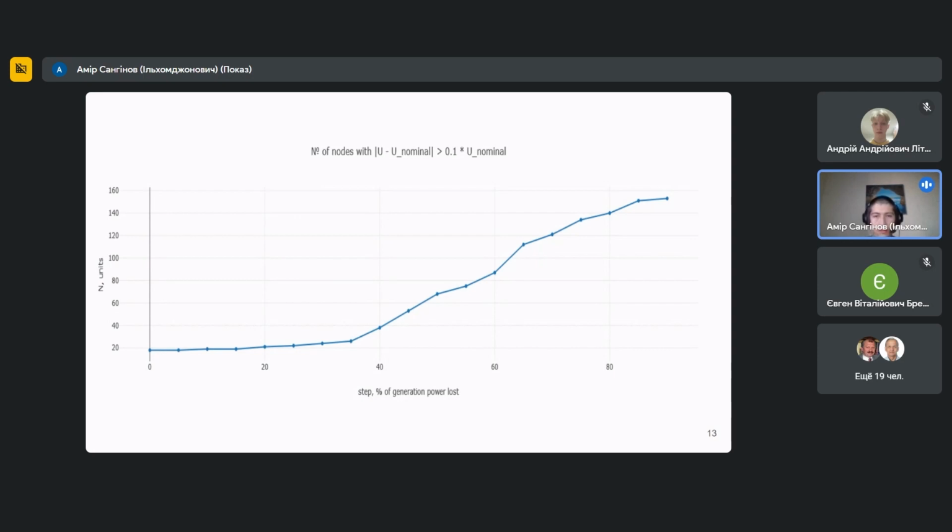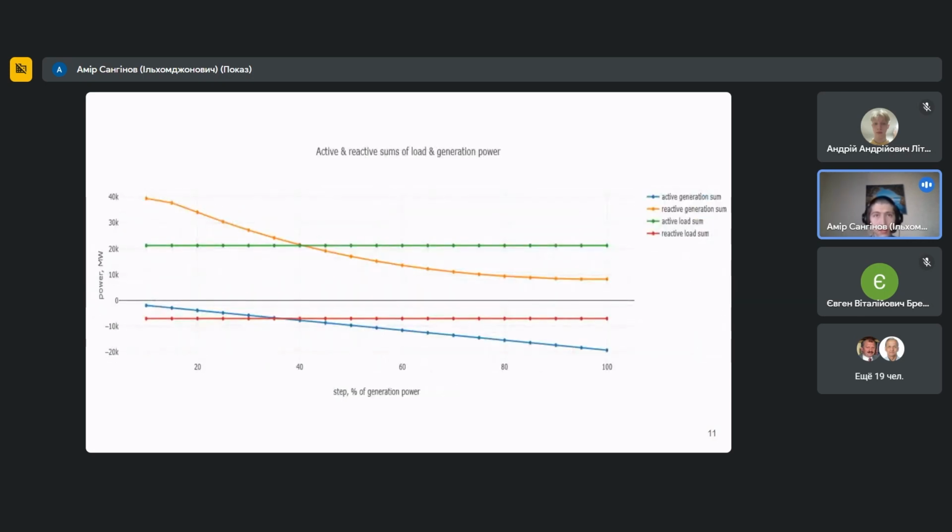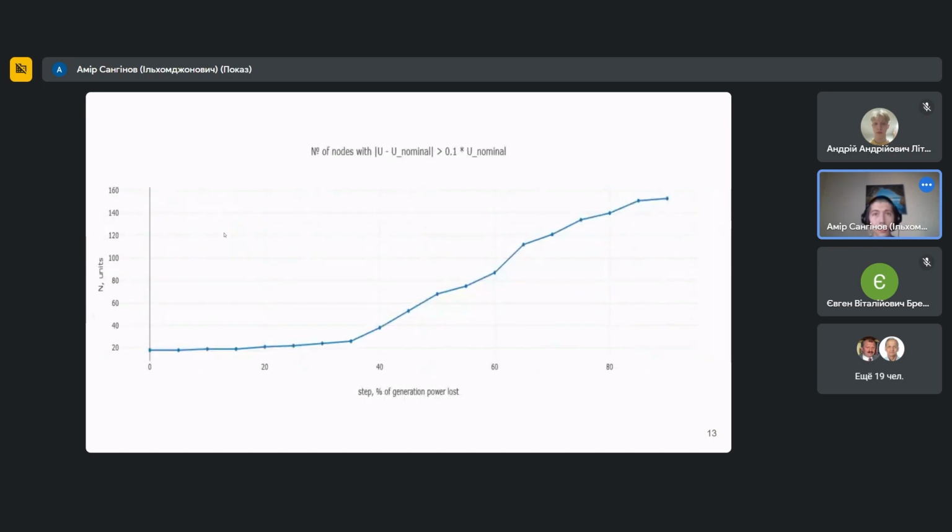We see these results because of the absence of the limits on the reactive power generation earlier, which raises the voltage levels and compensates some of the results. So for instance, here, if we did have more limitations, we would see more nodes, potentially all of the nodes, with significantly reduced voltage below nominal, not just 36%. And we would also see the formation of islands.